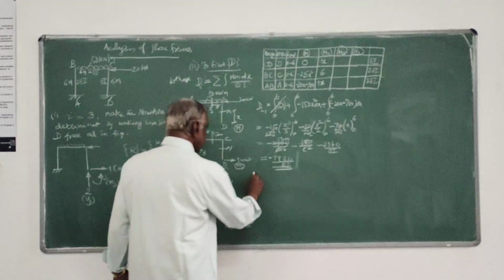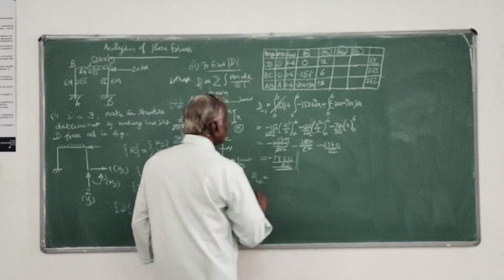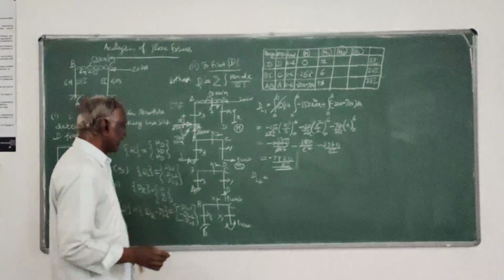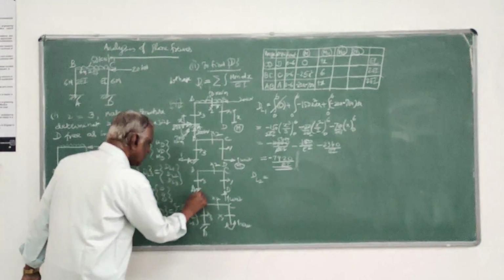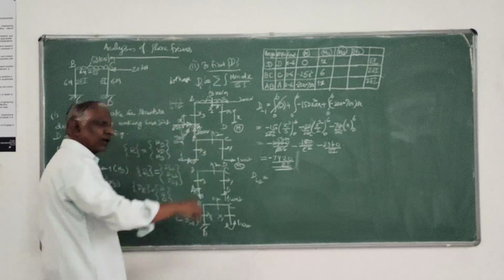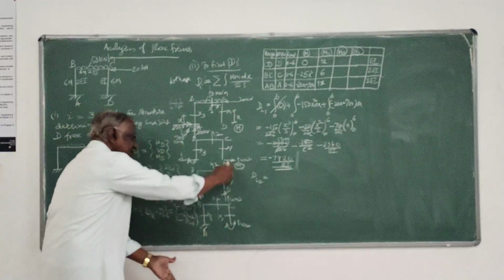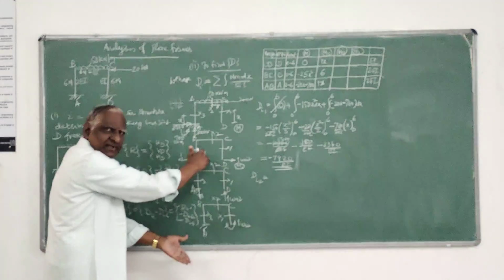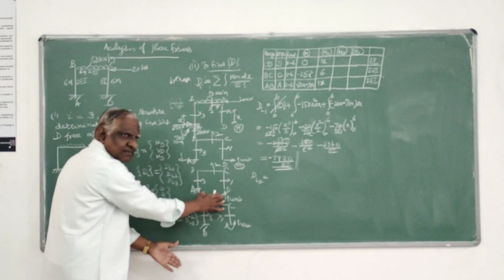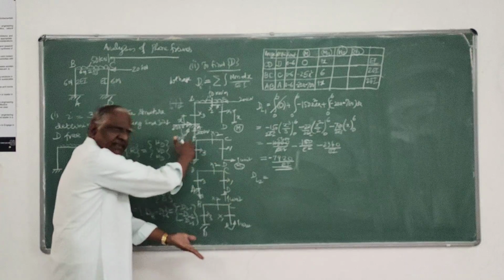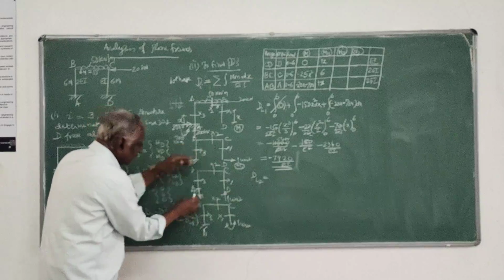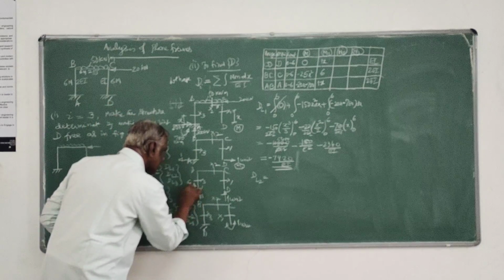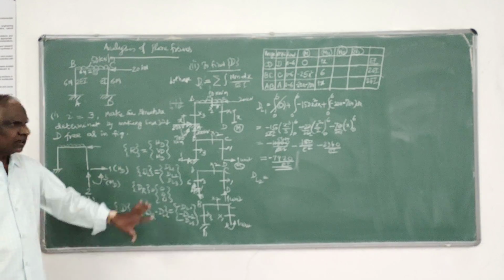And next, dl2 on the same lines. I have to work out m2. m2 means this figure. This is 1 upward. Here it should be 1 down. Right? This gives a moment, because this is not in equilibrium now. This gives a moment in this direction, that is 1 into 6, in the anti-clockwise direction. So here there must be a moment in the clockwise direction, that is 6. Is it clear? Now this is in equilibrium.